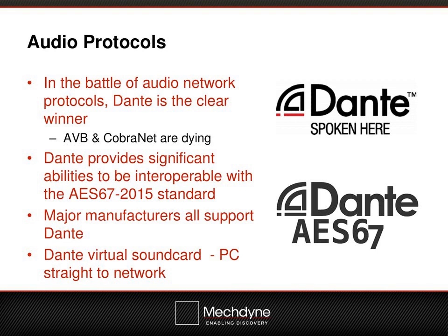As far as audio protocols, in the battle of the audio network protocols, Dante was definitely the clear winner. AVB and CobraNet were kind of dying players in the audio network protocol space. Now, there is an open standard called AES67, and Dante and AES67 are very interoperable. Not guaranteed to be interoperable, but a lot of availability to be interoperable between those two standards. So we're very excited about that.